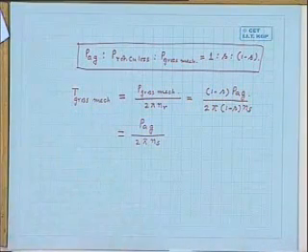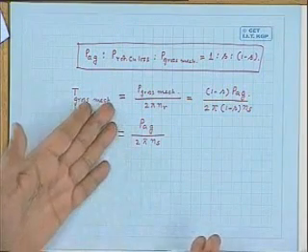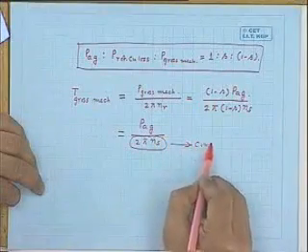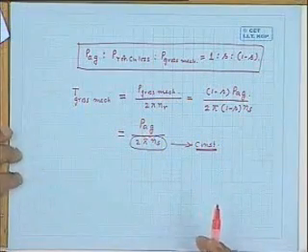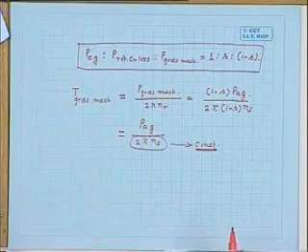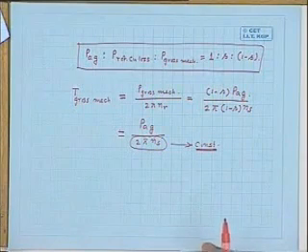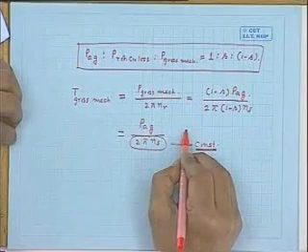So remember that to calculate the gross mechanical torque developed by the machine, either you calculate actual mechanical power developed by the machine divided by 2 pi NR, or simply you calculate air gap power. Don't go up to that extent. Simply divide it by synchronous speed, which is constant. This thing is a constant of the machine. It does not change with loading. Therefore, in other words, we can say air gap power is a measure of torque developed by the machine. Gross mechanical torque developed by the machine is the same as the air gap power.